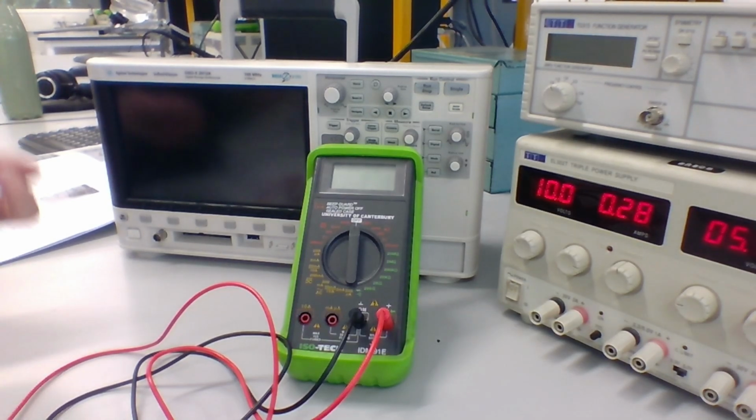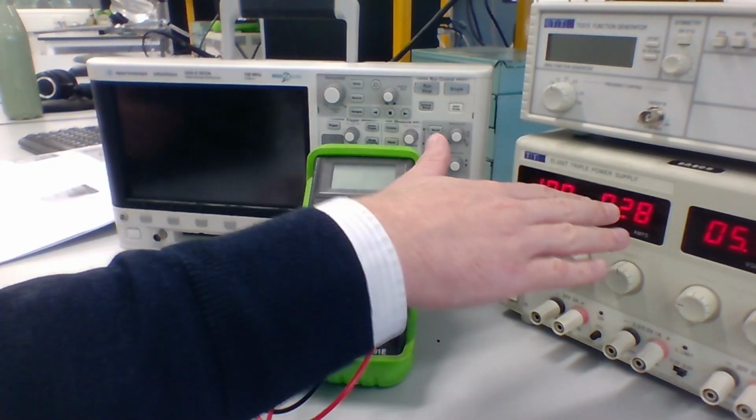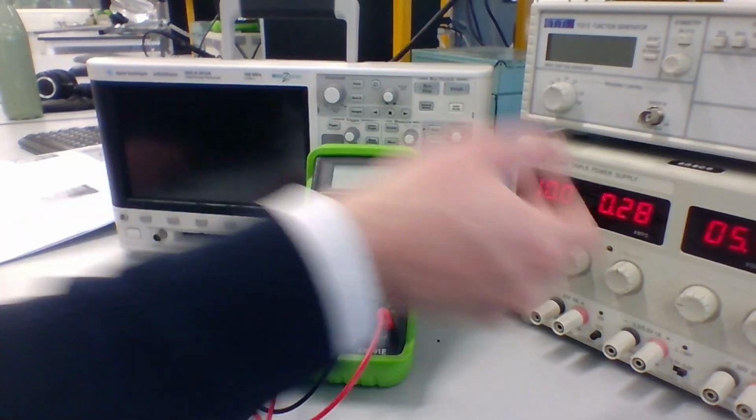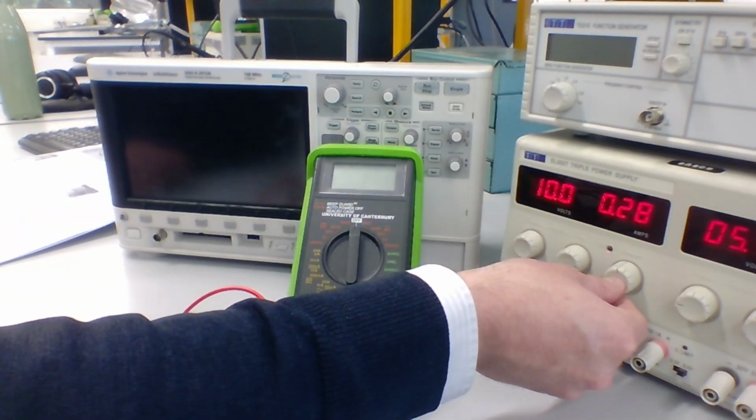So if in our circuit we had a short circuit somewhere and we had no current limit, we will in theory get an infinite amount of current. In practice there will be some limit on it, but without setting that limit appropriately, that could be quite a large amount of current, and that could damage or destroy devices in our circuit. So we always want to have a current limit set.